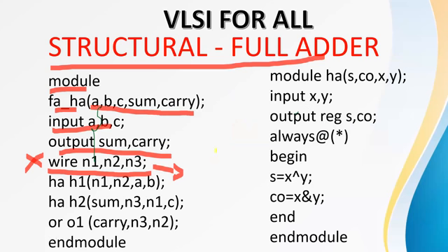Okay, see, what I have to declare initially is the functionality of the half adder. What is the functionality of the half adder? Sum is equal to X XOR Y. I'm defining X and Y both as the inputs, and S and C naught are the outputs. You can write it any way. You can write A, B, or X, Y, Z, anything. And in ports also, you can declare the input first or output first. Anything, but you have to mention it properly while declaring the input and output.